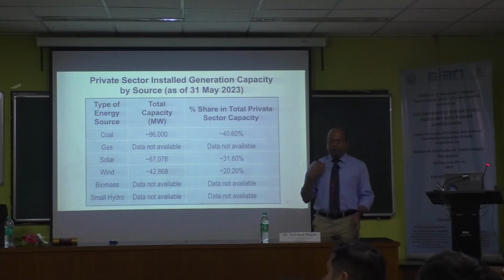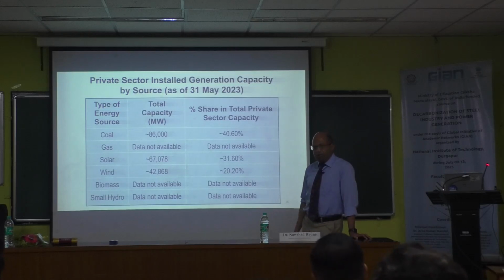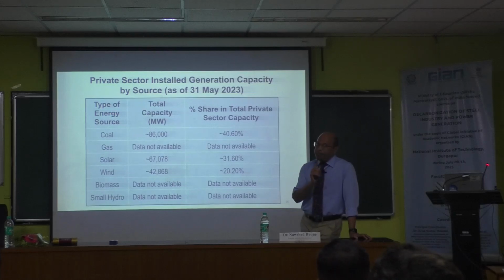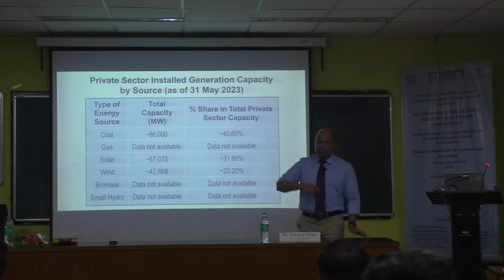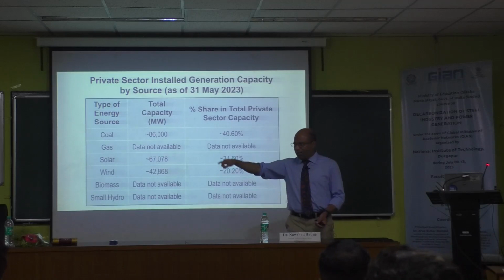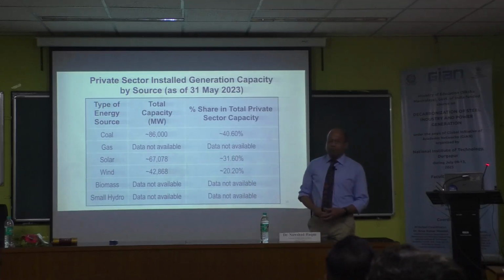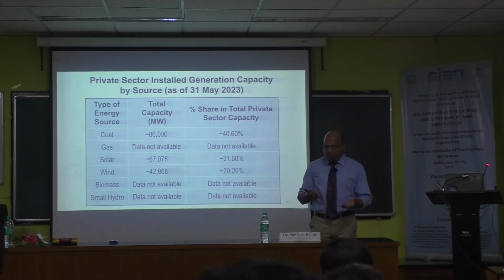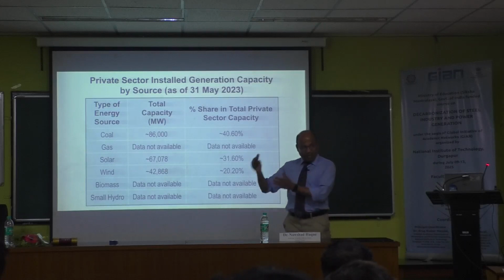Later you might not. In my own home, I have got 6.6 kilowatt solar, sorry, not megawatt. Megawatt is new, you know. 6.6 kilowatt panels, with a 5 kilowatt inverter. So the limit is 5 kilowatt even though I am producing 6.6. It should be a bell curve on a nice sunny day, but it goes up, then flat, and then comes down. Every day like that. My 5 kilowatt system produces about 8,000 kilowatt hours per year, while my own need is only about a third. So I produce 3 times more, my own need plus my 2 neighbors.